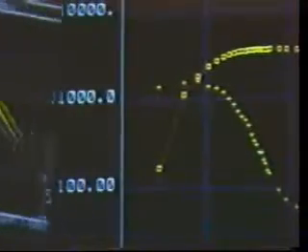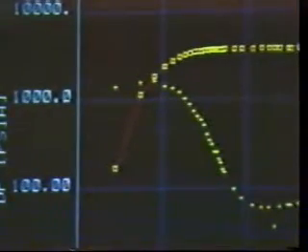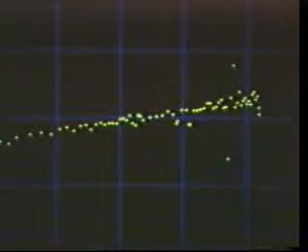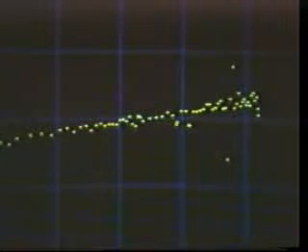The derivative plot is determined with respect to the superposition time function. Basically, the plot is made by calculating the speed at which pressures are changing during the transient. Generally, the derivative plot is calculated on a computer. There are several methods and choices available for computing and smoothing the derivative values, and it should be noted that any measurement errors made when conducting the test can contribute to creating a noisy derivative.